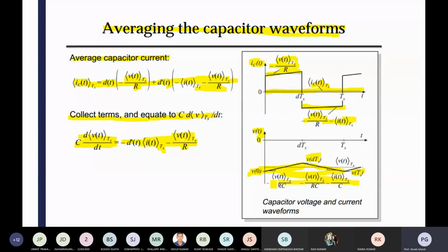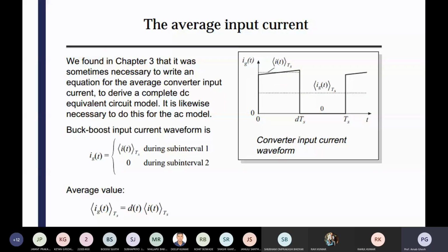That's why for the zero instant you will get some bias value or the fixed value, then it is slowed down. Okay, after that again it will be ramped down, then ramp up. Okay, so two expressions will be there, and finally we will get that dotted line, which is your average value. Okay, so that is the average through the cycle, that is your Ts.